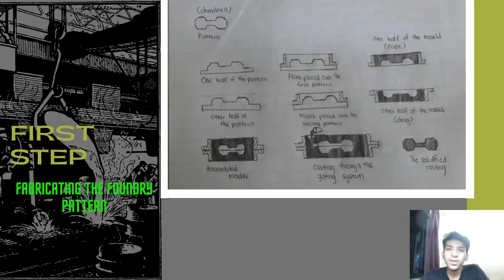Cores are internal mold inserts that can also be used if interior contours are needed, but are typically disposable after one casting. The type of pattern and its material is dictated not only by the desired part dimensions but also by the number of casting needed from each mold.